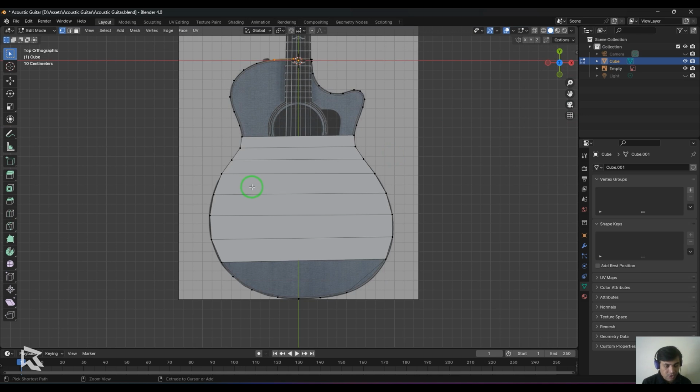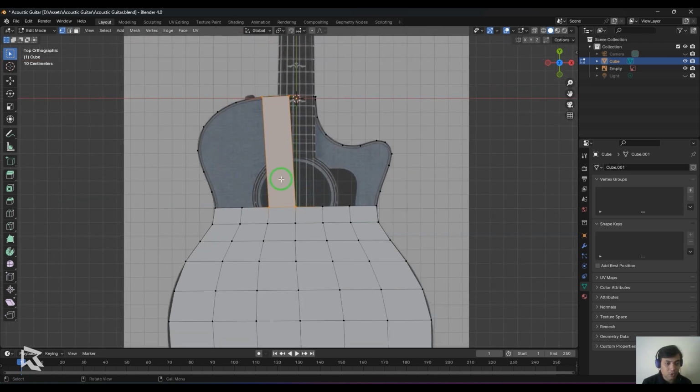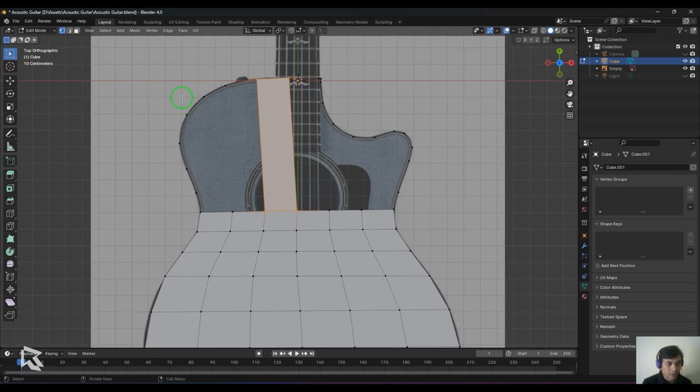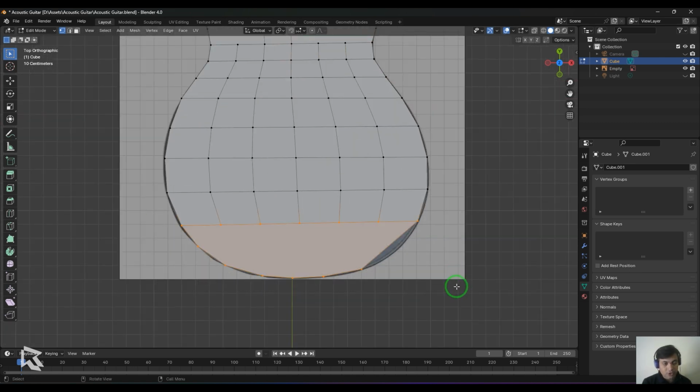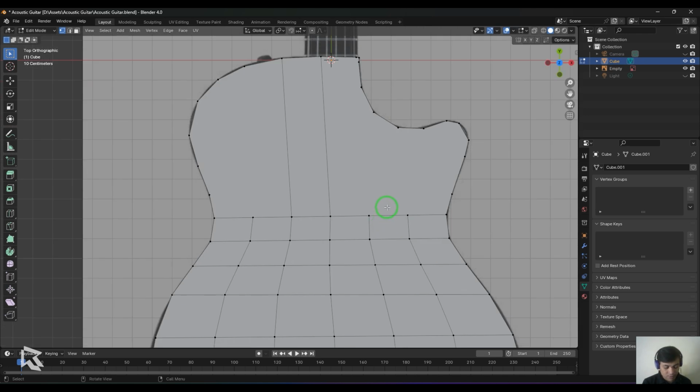Okay. So I press Ctrl R and then increase the subdivisions, and make sure that I've added sufficient lines there, and then press F, and you should be able to see those lines are well connected now. Now you can select these points here, press F, and then select these points, press F, and then select these points, press F. So it all fills those points. Now I just press K and then start connecting those lines here. So that line takes a turn and connects over there.